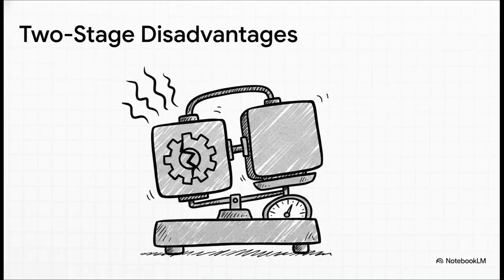Of course, there's always a catch, right? To get that independent control, engineers have to swallow some pretty notable trade-offs. The 2-stage arrangement actually suffers from lower power conversion efficiency, simply because the power is forced to pass through 2 distinct processing stages. It also has slightly lower reliability because you're adding more fully controlled switches and a chopper circuit into the mix. And finally, because of that extra boost stage, the equipment itself is significantly bulkier and heavier. It's your classic engineering compromise.